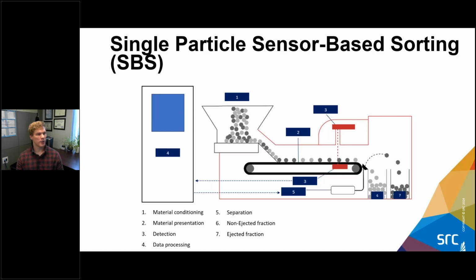So there's really two types of them. There's incidental ejection. So that's if, like, for this example, if two particles were moving over this belt and they're very close to each other and the ejection mechanism fires, well, it'll eject the particle you identified for ejection, but it might also incidentally clip another particle, and then they both get ejected into the bin. So if you were ejecting waste, you might get the waste particle and a piece of ore might accidentally go. And these don't happen at high frequencies and high volumes, but there is a difference between that and actually what's happening ideally.